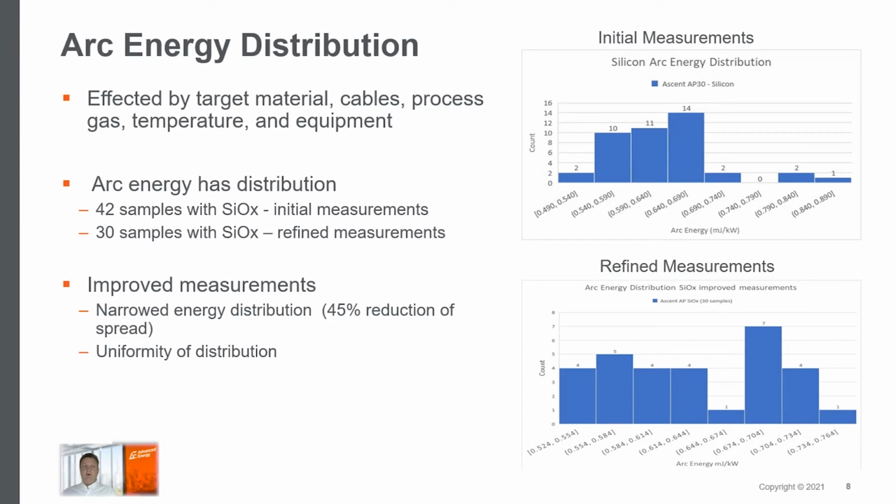Also, the trigger type: we found variabilities in how we triggered. We started off triggering on either a falling voltage or a rising current, and ultimately we switched over to triggering off of the shutdown time. That also stabilized the measurements. And there's naturally going to be some error introduced because humans are manually finding the cursor placement and determining the 90% of the process voltage.